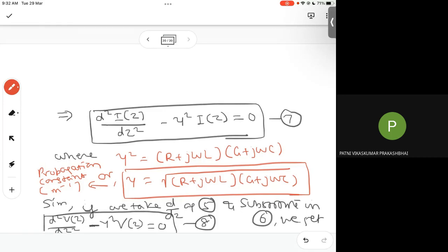And it depends upon the frequency. Obviously, if you change the frequency of the signal, your propagation velocity is going to be different, your attenuation is going to be different. That means the loss in the cable is going to be different, because these are all dependent upon the equivalent parameters, RLGC. So basically, this is a very big concept which you understood, and now it will become very easy to understand various other parameters which characterize a transmission line.